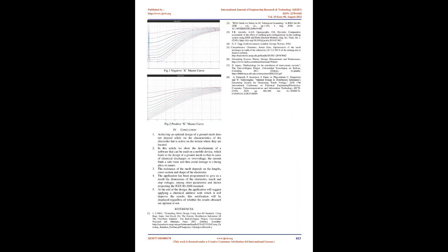Method for calculating soil resistivity. Since the IEEE 80-2000 does not include a specific method for calculating soil resistivity, it was necessary to resort to investigating various types of evaluation for it. Concluding in various comparisons that the most correct method based on theory and calculation is the Tagg method, known as the Tagg equation, through which I determine some master curves that simply consist of giving values to the variables k, h, and a, obtaining values of ρa/ρ1 for each case.